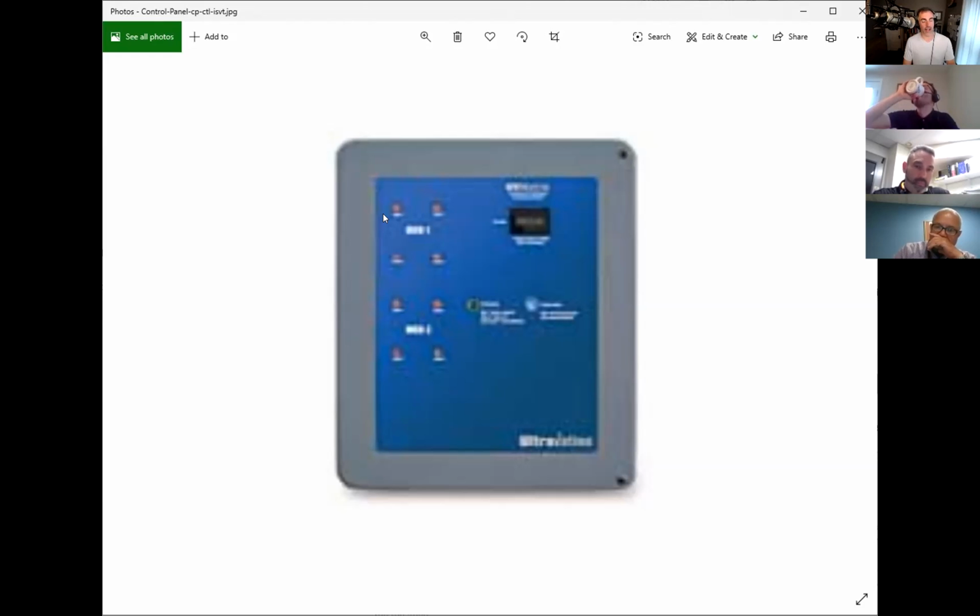So it's just saying, hey, great, I don't have to stick my face in there or look in. I can tell just by walking by the control panel that these lamps are in operation, and you guys are tracking them. They'll have end of lamp life because these are T3 bulbs, so you'll have a PM cycle of every 2 years to change the lamps out. And if a lamp fails, you're going to see it right on the remote control panel. So that's all you're looking for.